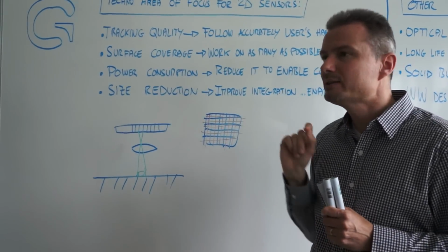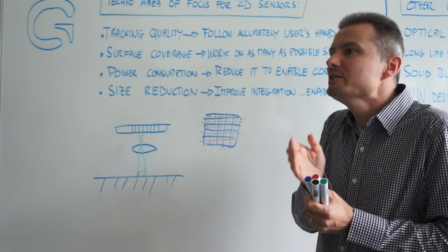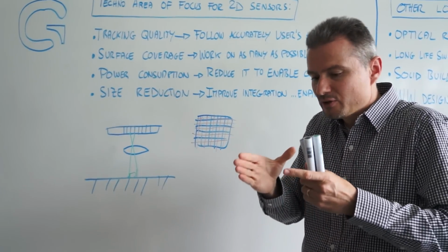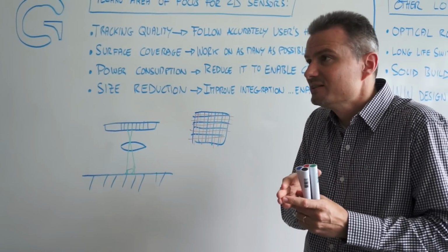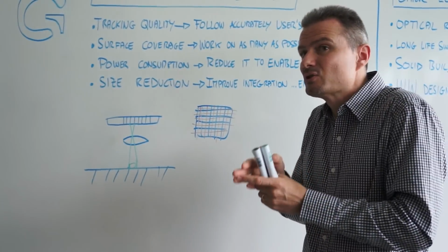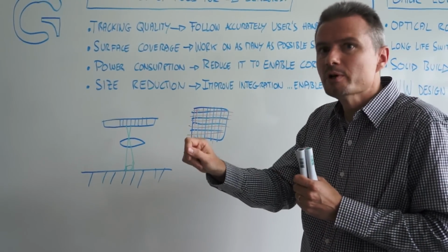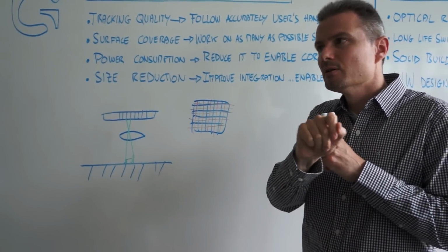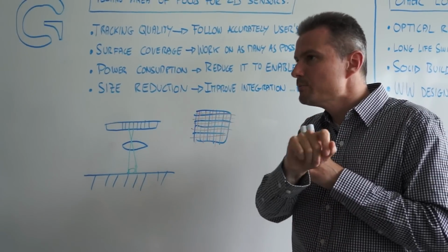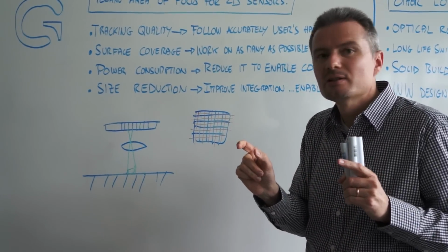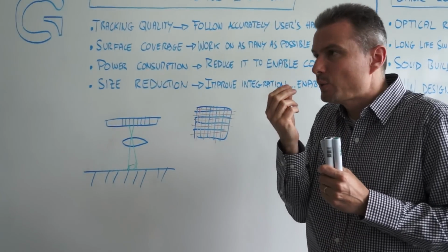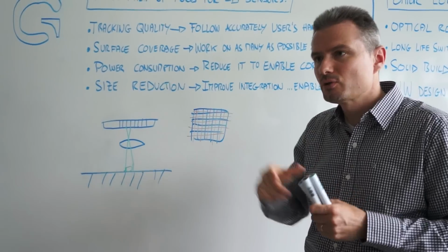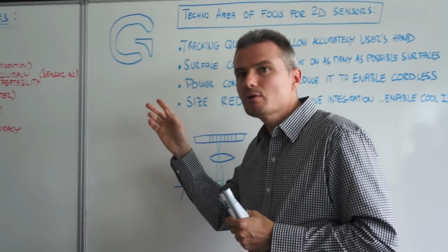It doesn't mean that if you have 8000 DPI, you have the capability to see more information than a system that has 800 DPI. It's just that you have cut the area in a smaller slice. It's just this. So it doesn't make your system less good. It's just a relationship between your hand movement and your screen movement. So in fact, DPI is a translation between how many pixels I travel when I move my hand by 1 inch. It's only this. It's not a question of any kind of quality of tracking. It's just a relationship, a magnification or a translation factor. Any question on this first?